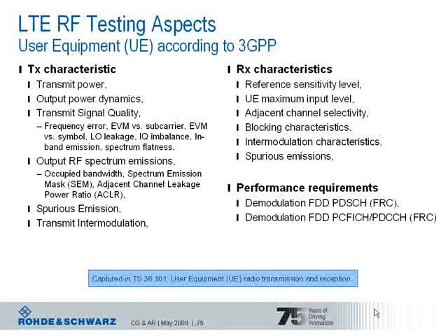For performance, it is of course essential to check the demodulation of the physical downlink shared channel under different conditions, as this channel carries user data based on a specified fixed reference channel. The second major performance requirement is the demodulation of the control channels, meaning the physical control format indicator channel and the physical downlink control channel. These channels inform the UE about the schedule decisions.